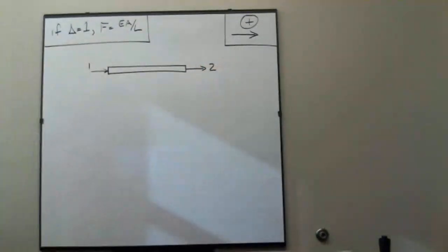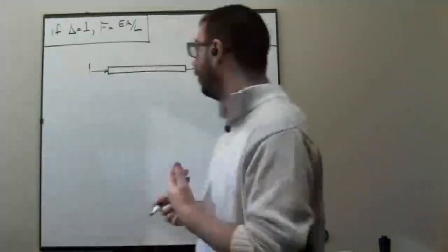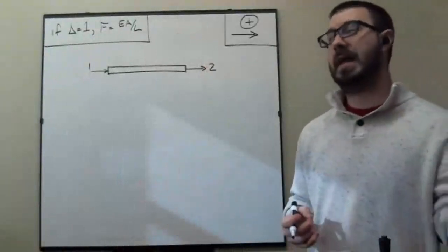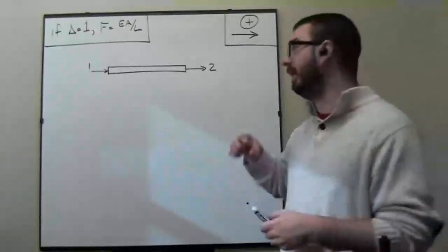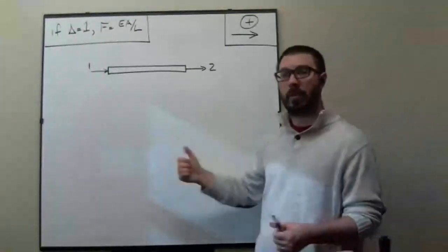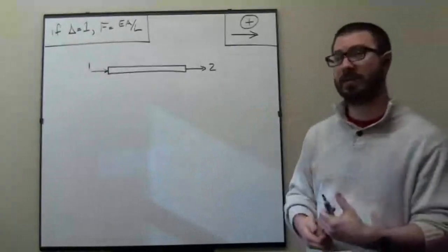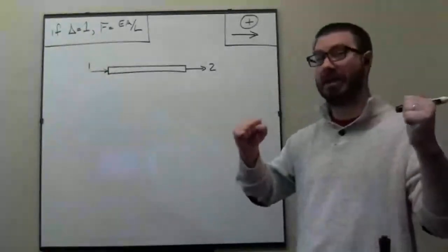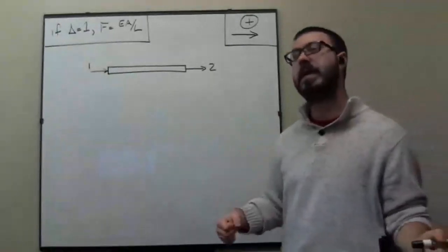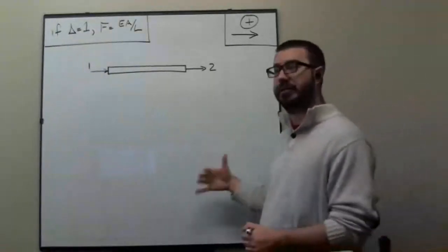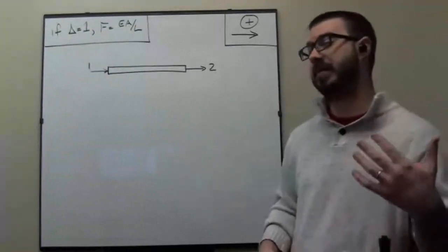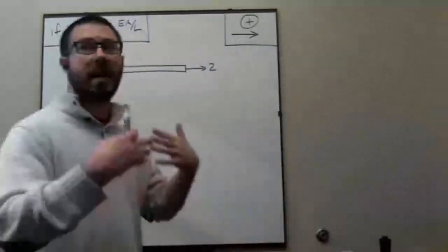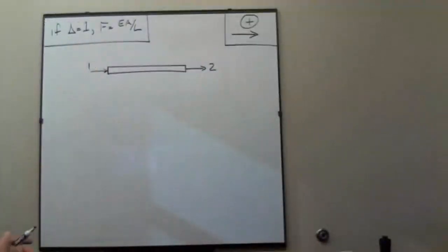So there's 2, okay? In order to derive the stiffness matrix, we're going to use what's called a direct approach. The direct approach is basically literally yanking on this bar or compressing this bar and then recording the forces that cause those displacements. That's what we mean by a direct stiffness approach. We're actually compressing the bar or yanking on it. There are other approaches that we can use to derive the K matrix. There is a very famous approximate approach called finite elements. The finite element method is just another way of developing this process.